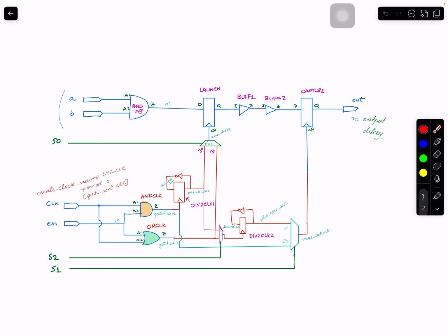So if you think about this, the select pin, I said, okay, it's coming from the port. Select pin of this multiplexer coming from the port as well as this one. So using S0, S1, S2, I can create case analysis and put this circuit in multiple modes. I can put this into kind of 8 modes, right? 8 unique modes, S0 for 3 combinations.